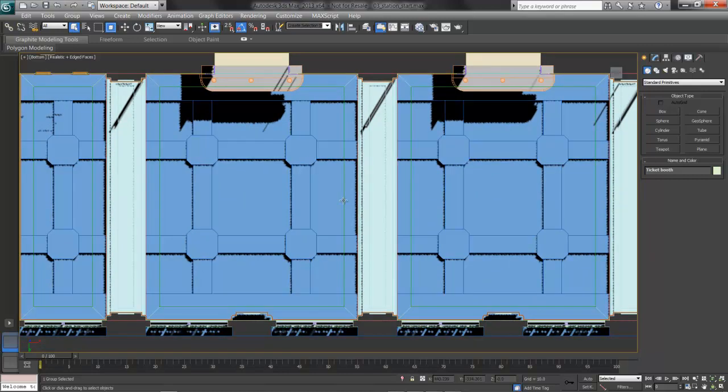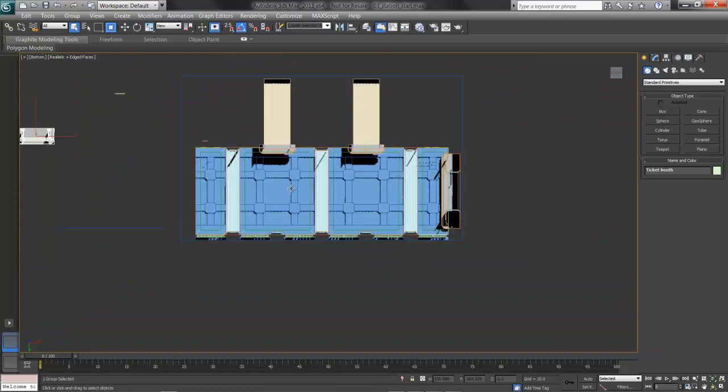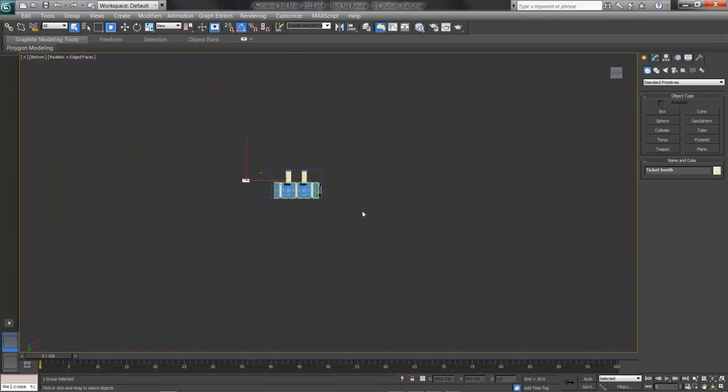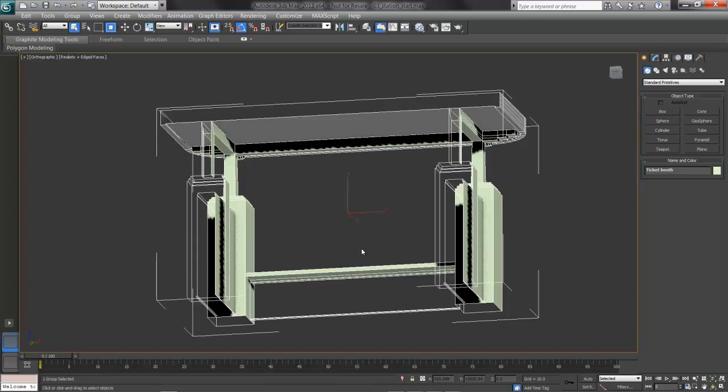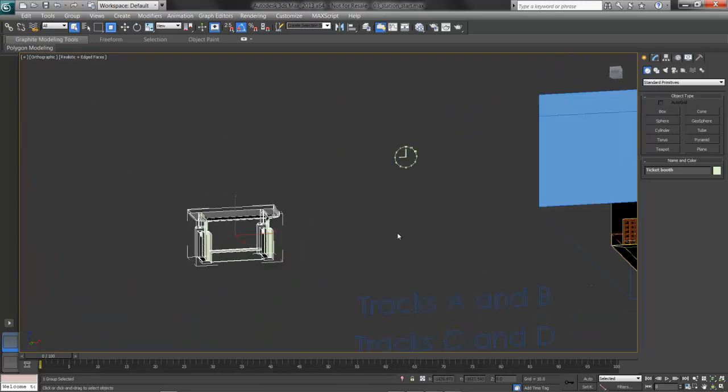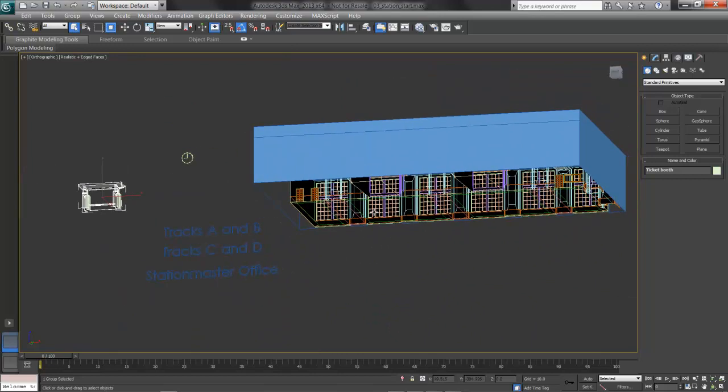We're working on good size monitors, and we have a lot of real estate available, and most computers have decent graphics power, enough to get in and see what's going on. So zoom in. When I teach, it kills me to see students working like this. There's all this empty space around, and they're trying to do something on this little bitty postage stamp right here, and not getting much done. So spin around, use Alt and that mouse wheel. Z to zoom extents. Click on objects to select them, and change around your views, getting to the best view you need to show what's going on.